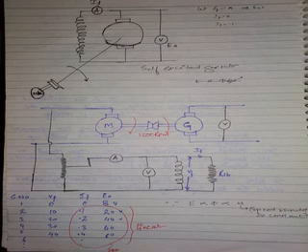Then when the generator is running at its rated speed, will the voltmeter deflect to any value? It will deflect if it has residual flux. It will deflect if the poles have residual flux. This is the field winding on the pole. The pole is magnetized already, field flashing. So under the pole, there is a small residual flux. So the armature conductors will cut the residual flux, and automatically what is produced? Small voltage. So if VF is 0, IF is 0, E0 will be around 6 to 8 volts. So OCC, if there is residual flux, never starts from origin. It will start with some small residual voltage value.